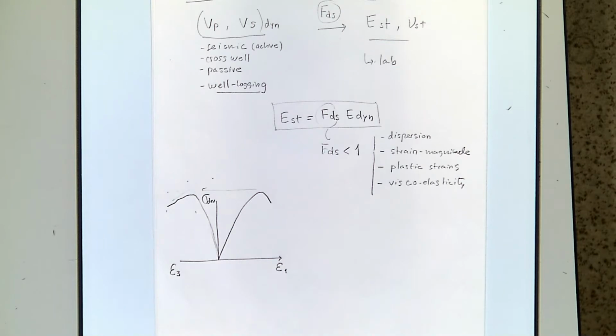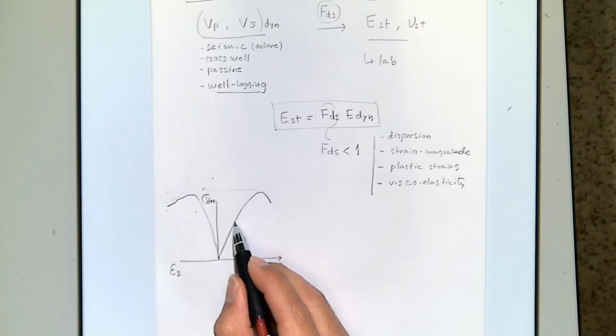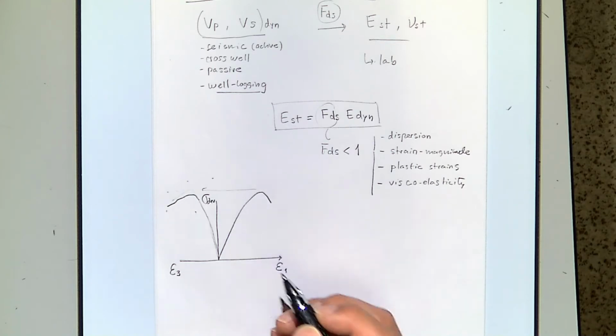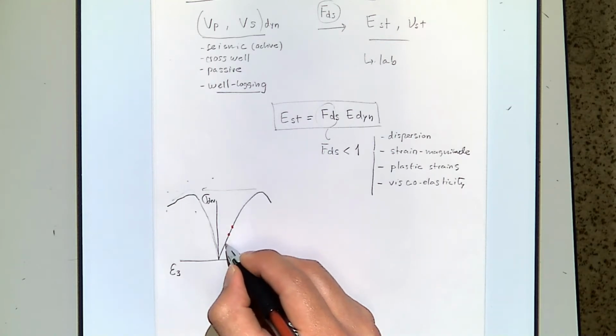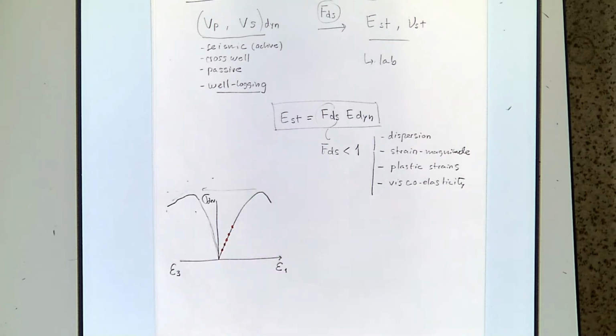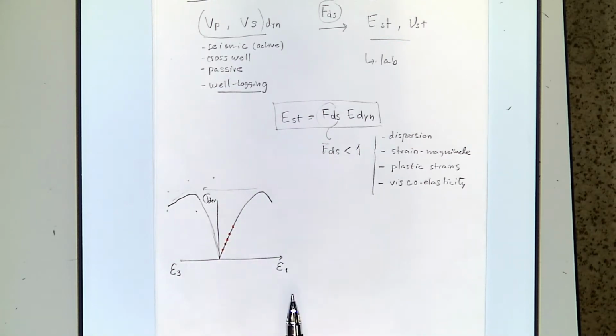And what I'm asking you is that before the point of 50% of the peak stress, take a couple of values here. Let's say 5. Measure the Young modulus at those locations. This is a real rock, so it's not going to be exactly linear, okay? These values are going to be similar, but are not going to be linear.